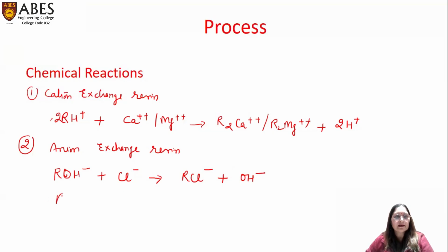Similarly, ROH- reacts with sulfate ion, taken up by the resin as R2SO4-- and releases the equivalent amount of OH- ion.